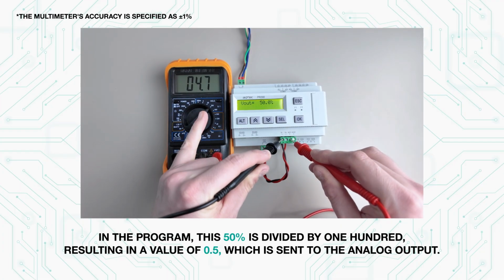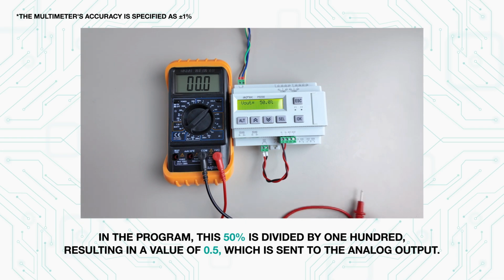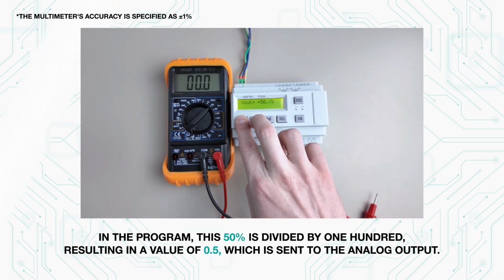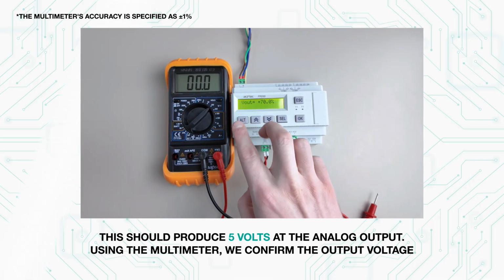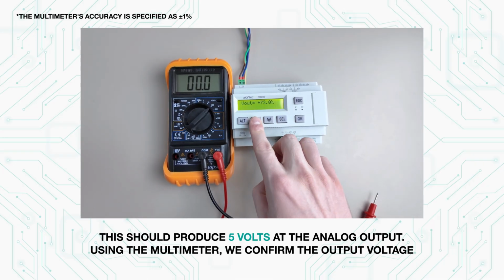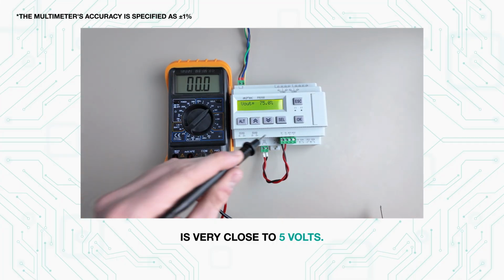In the program, this 50% is divided by 100, resulting in a value of 0.5, which is sent to the analog output. This should produce 5 volts at the analog output. Using the multimeter, we confirm the output voltage is very close to 5 volts.